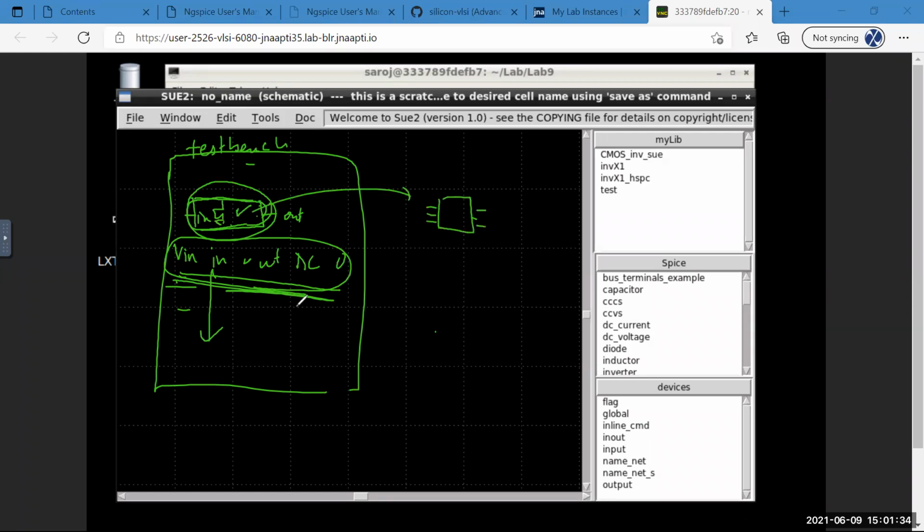And you test it the way you tested it on your test bench, by applying an oscilloscope, waveform generator, and viewing the signal and so on, right? So it's the same sort of principle. Whatever you want to fabricate or design, keep it in a separate symbol, and just use the test bench and instantiate that. Don't put ideal sources and resistors and all that in your core design; you want to avoid that.